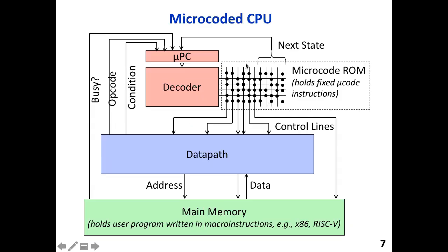So people who write the microcode ROM, these are the microcode programmers. They're the designers of the instruction set architecture. And what they'll do is they'll create new operational codes, or opcodes. And these will be machine code instructions. So for example, you could have a special instruction that says no operation, which does nothing for one cycle. And that could be inserted for the purpose of delay.